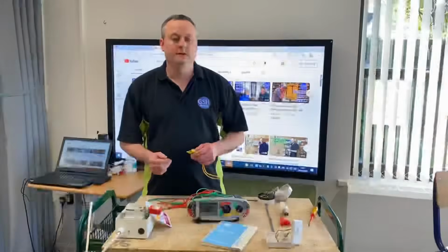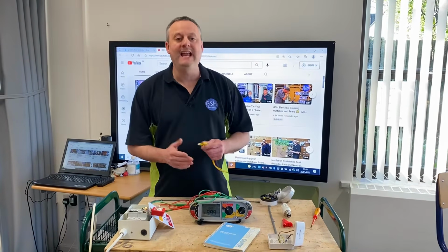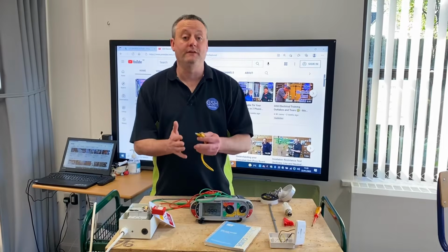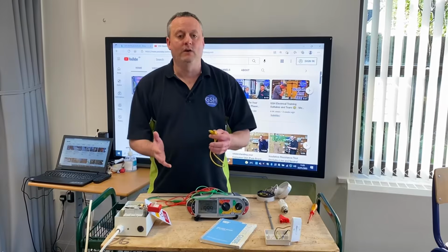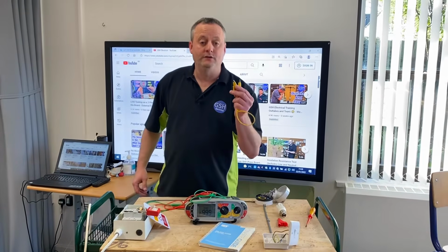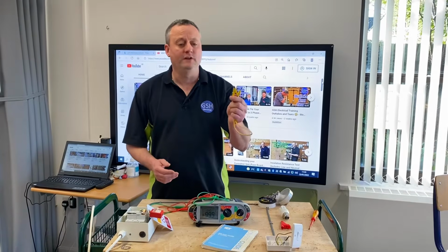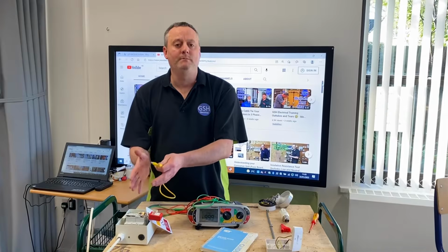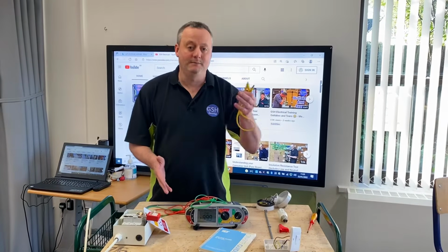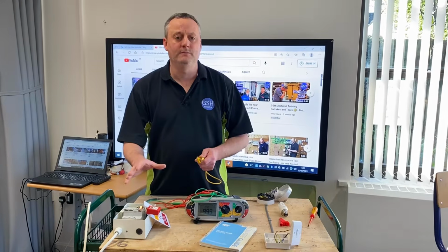So hopefully that's given you a guide on how to carry out that first test that you're probably going to carry out in any electrical workshop up and down the country on the first circuit that you install, which usually is a one-way lighting circuit. I've used my R1R2 link, and I think I've confirmed from my point of view that this is a must for college settings. It meant that I didn't have to unscrew any additional terminals within my consumer unit that obviously can become damaged, and it's quite expensive for colleges to start replacing items within consumer units.